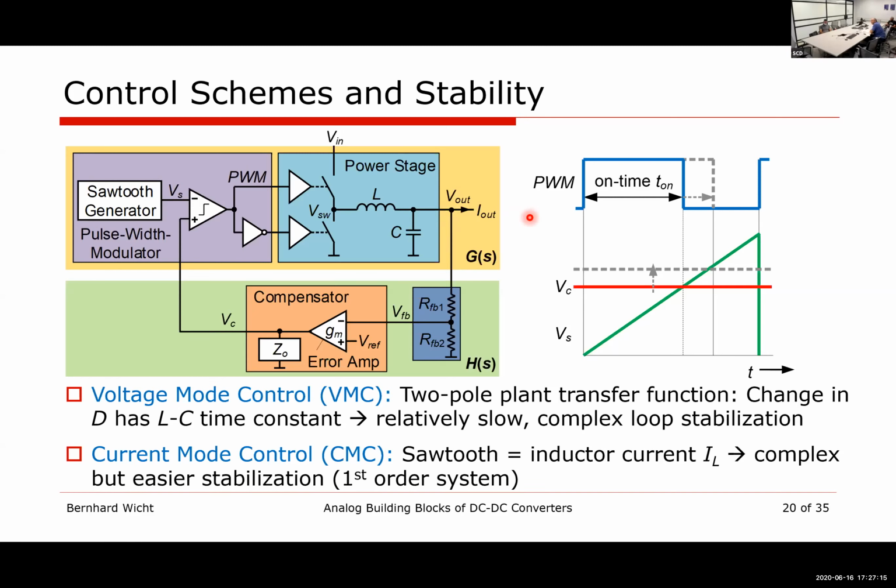Okay. So your best solution would be some low dropout, like an LDO regulator. Yeah, the LDO. Of course, if the input voltage is quite large, you would first use a buck regulator, a switch mode regulator, to bring the voltage down by a big portion, and then leave only a little bit of voltage that the linear regulator can handle.